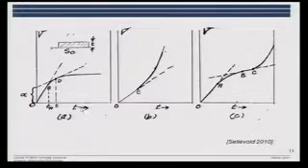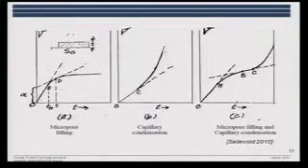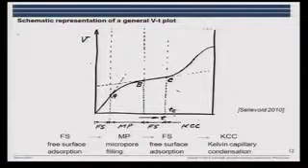And if we look at sorption isotherms, this would be the first part where we have the free surface adsorption, and then we have the filling of the micropores. Here we have an example of only capillary condensation, and here we have the combination, and that looks like the sorption isotherms we see for cement-based materials. So the latter part here, the micropore filling, where we have a decrease in the slope, and the next, capillary condensation, and micropore filling and capillary condensation. And here you see it again.